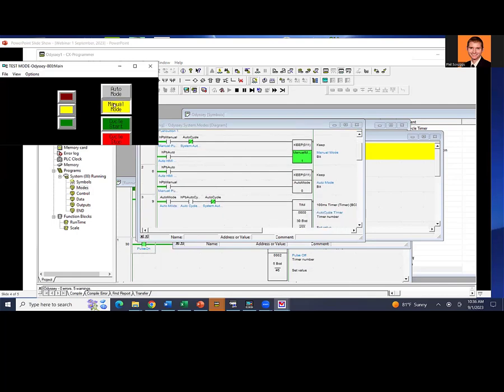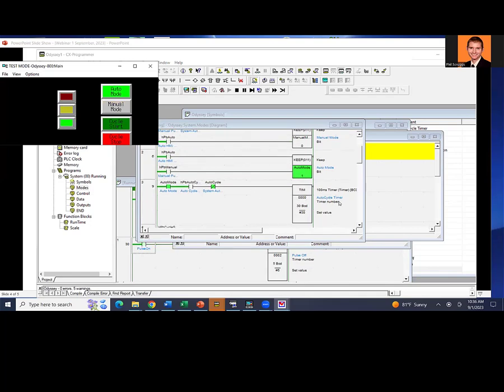Auto cycle, go into auto mode, hold the cycle start button, you'll see the timer run. So this is a BCD timer. We can get off into that a little bit later. I have some instructions if you don't understand what BCD is. There it's timing, it goes down to 0. You saw it count here. We'll do a cycle stop again so you can see it again. Watch this number and you'll see this timer time down. That's 3 seconds. 1, 2, 3.